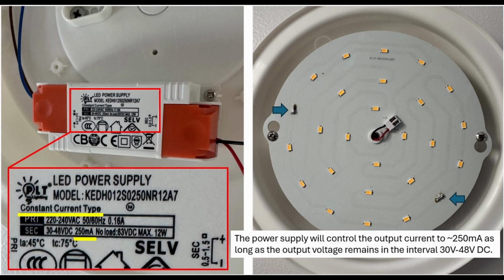So I had an LED light fail the other day, and I thought I'd share the fault troubleshooting with you guys. Typically when an LED light fails, it's the power supply that gives in, and you can test the power supply by either swapping the LED strip or, more advanced, with some external resistance, and see that you get the current that is expected at the voltage drop that's displayed.